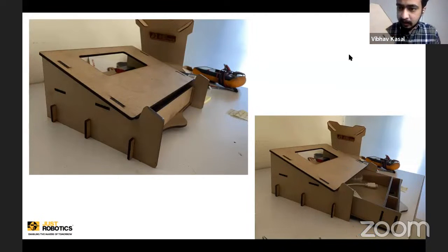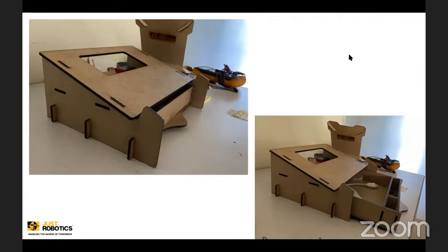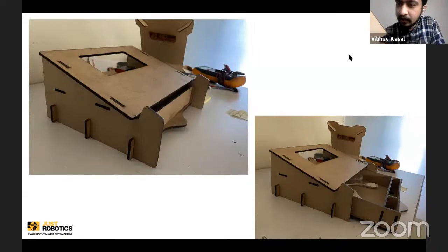This was laser cut. Can you see there are burn marks here? You will not see a burn mark here, but you will see one on this edge. The laser cutting machine is going fast, and it is not leaving so much burn mark on the straight lines. But as soon as there is a curve, it slows down a little, and there is a burn mark. And a burn mark also gives an effect.